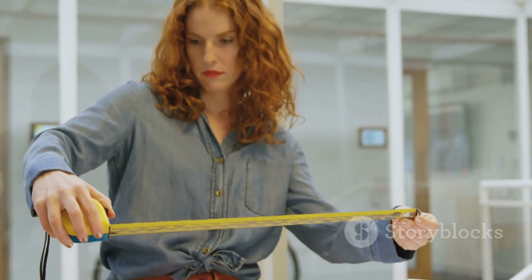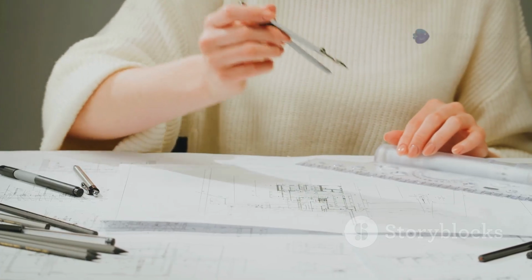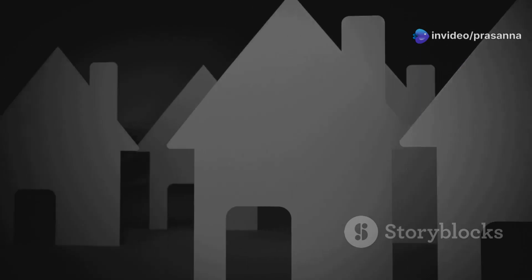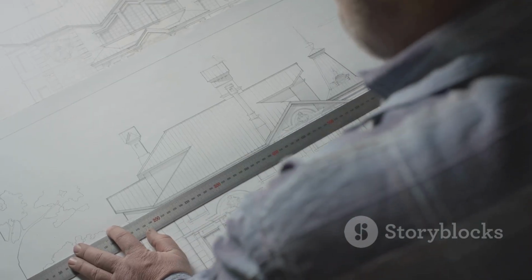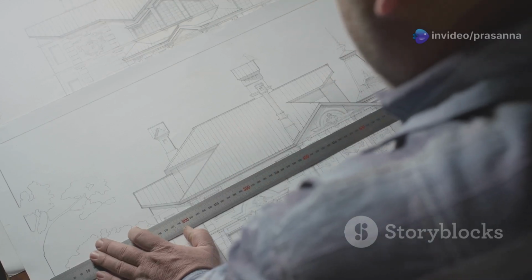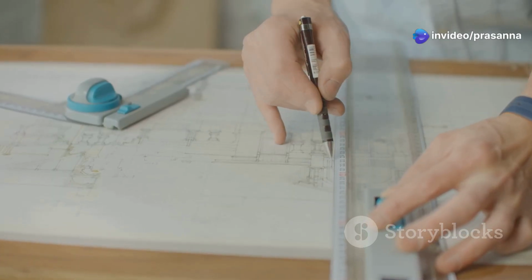It is important to be accurate during this tracing process. Double-check your measurements. SketchUp's snapping features will help you connect lines precisely. This step creates the basic footprint of your house in a 2-dimensional form within the 3-dimensional SketchUp environment. After tracing all the necessary outlines from your AutoCAD plan, you have a 2-dimensional base in SketchUp. This 2-dimensional base is perfectly scaled according to your original drawing.